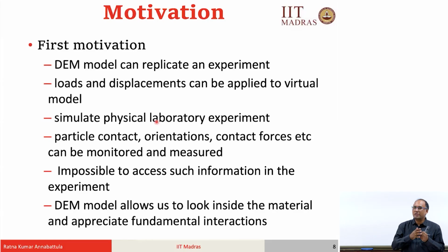So, the number of particles establishing contact and the amount of contact area will be changing as a function of load, and hence it is not the same material every time you are compressing. Every time instance you are actually going from one material to another material, in a macroscopic sense. That is the reason why it will not in general have the same slope, it will change its slope, and that is what we perceive as a nonlinear response.